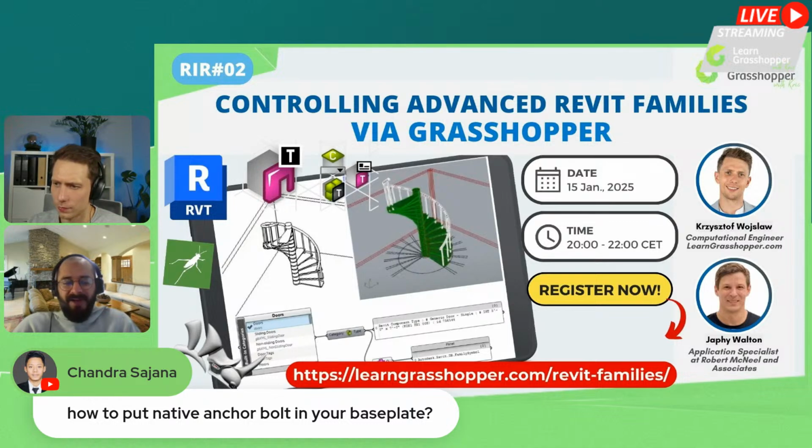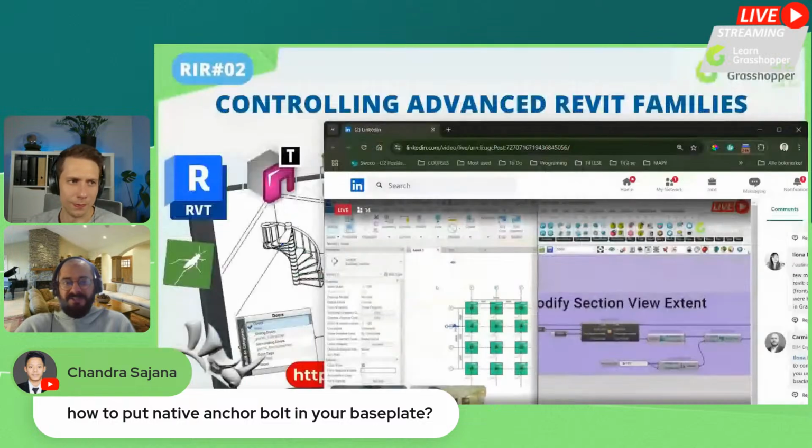So I created this tutorial where I showed that if you have a detail item, you can create this kind of anchor bolts as a parametric family and connect your parameters to that family. For instance, if you have a specific type of bolts, you can just place them using the Add Detail Item component in your sections, and simply tag those sections.